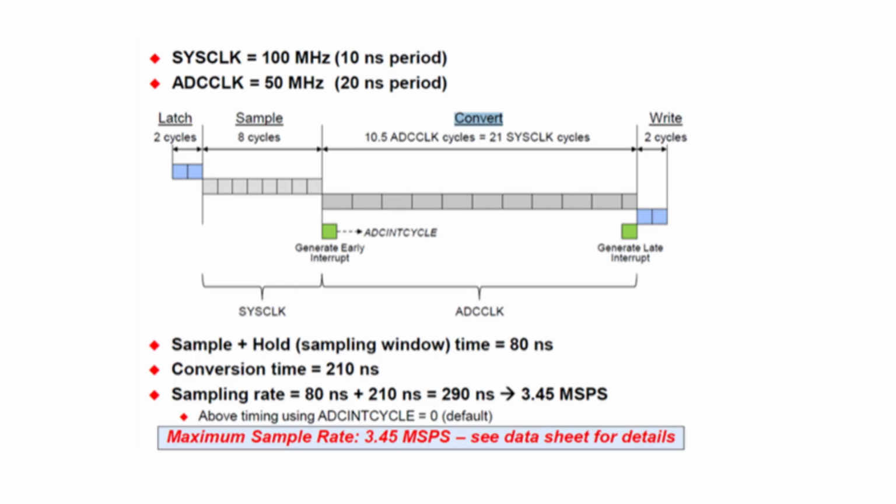How do engineers typically approach this tuning? It's about understanding the goals. If maximum resolution is key, you'd likely use oversampling and digital filtering, accept the slower effective sample rate, possibly use a longer sampling time for stability, and maybe a moderate prescaler. If maximum speed is paramount, you'd use the shortest sampling time your source impedance allows, maybe skip oversampling, and use the fastest possible ADC clock, smallest prescaler, that still meets the datasheet limits and gives acceptable noise.